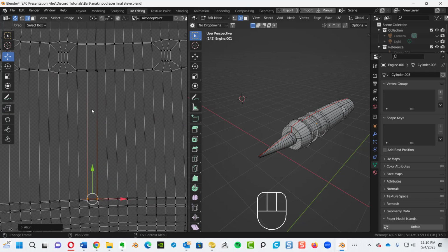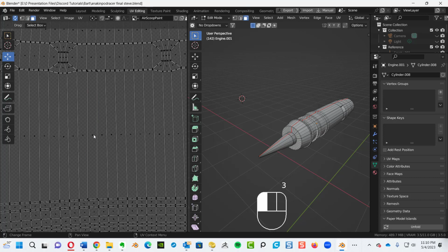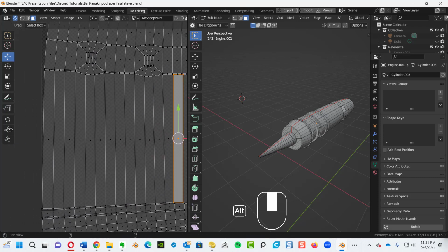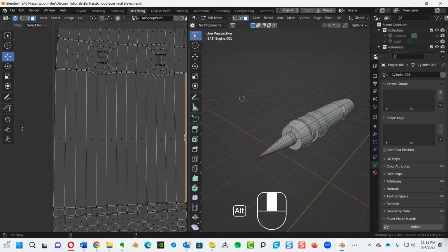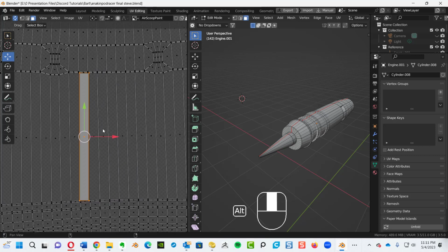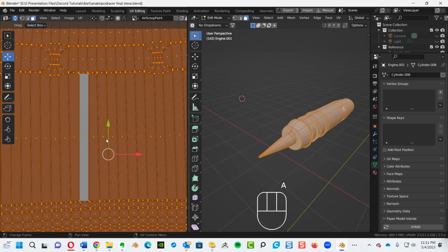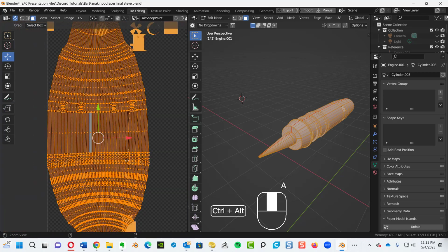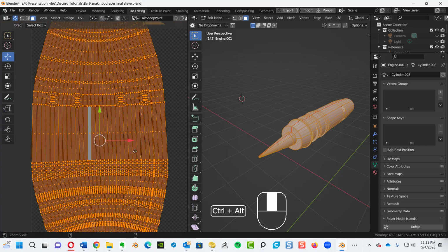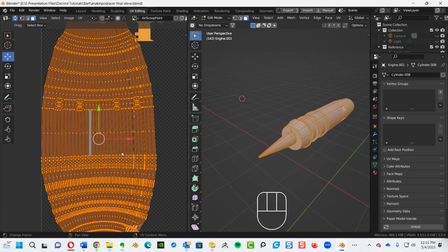Now go to your face editing mode, face view, select that face. All right, so that's the one that I have perfectly aligned. If I have any doubts, then what I'll do is bring it over to the edge. Yep, that's it. Okay. Now, A key to select all. Now, if you take a look at this, the original auto-aligned shape is much lighter.